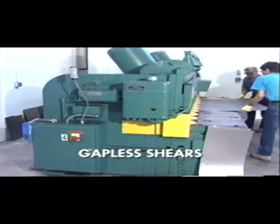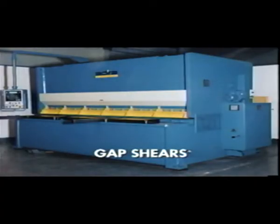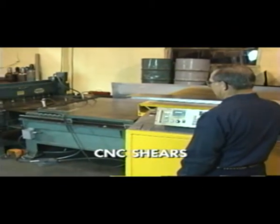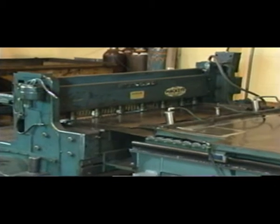Gapless shears have side frames which support the power unit and are joined together by the bed and crosshead. Gap shears are used for squaring sheet stock and producing blanks. Because of the gap or throat opening in the sides of the frame, they can handle larger sheet lengths than a gapless shear. Right-angle shears employ two sets of dual blades set at a right angle for simultaneous cuts along two axes. CNC shears can be programmed to shear a variety of lengths from a single sheet. The sheet is automatically repositioned in the shear for each cut.